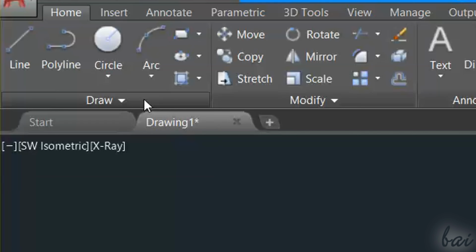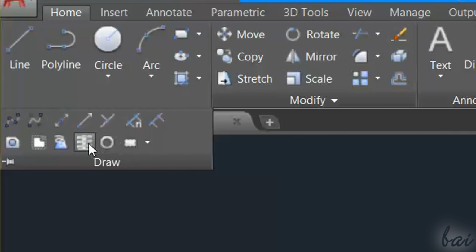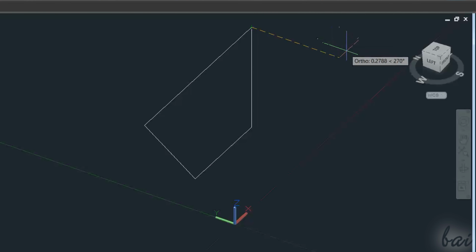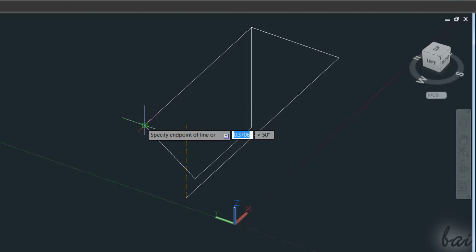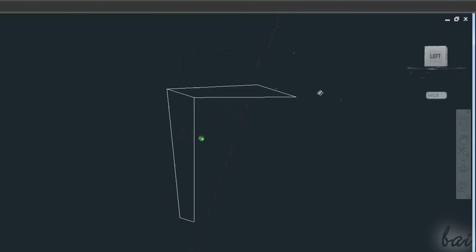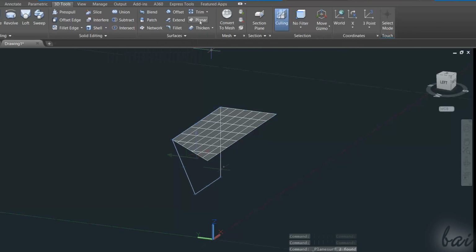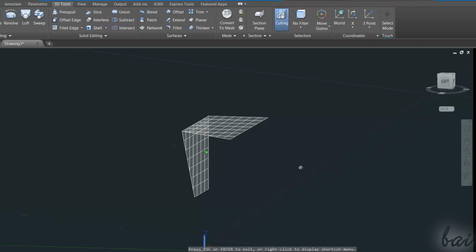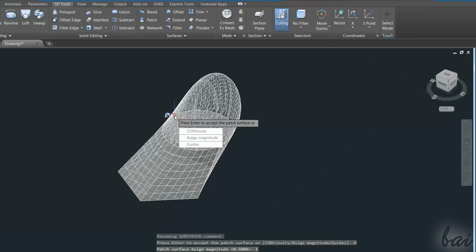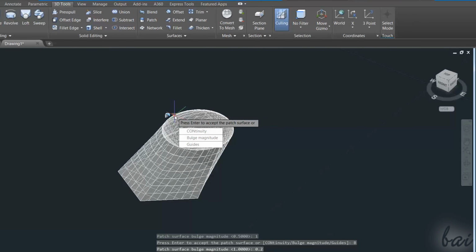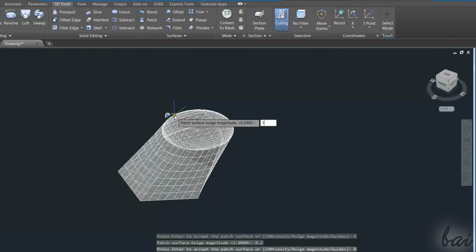To drop a very simple non-planar surface, you can use the 3D Polyline tool to create closed paths, each laying on a single different plane, and then creating surfaces by using the Planar Surface tool. But to create more complex non-planar surfaces, you have to use other tools inside the Surfaces section.